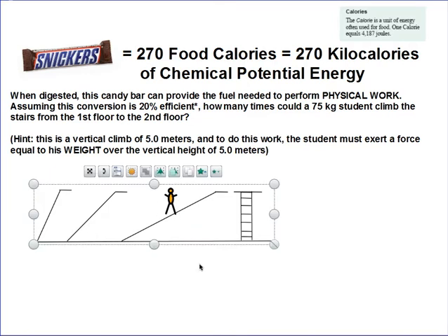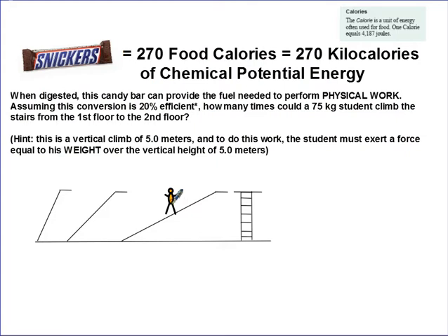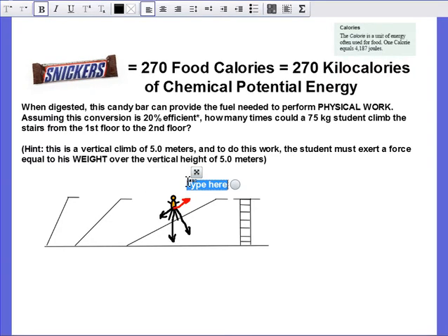Let's consider him being on a ramp or an inclined plane. As we talked about before, the weight force acts always downward. Well, we would typically resolve that into two components, a weight force into the plane and a weight force down the plane. Well, the shallower that angle, the less the weight force acting down the plane. So what he's going to end up having to do is just exert a force up the plane that's equal to this component. So what he ends up doing is he's exerting a fairly small force, but over a pretty big distance. So he's using an inclined plane to exert less force over a greater distance. He still does work equivalent to small f times big D.